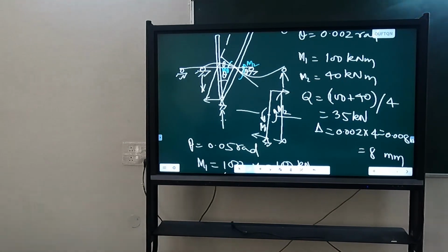What are the steps we have followed till now? At last, while taking the ductility, I have considered the ductility of the beam which has low ductility, that is beam 1. It is coming 10, and for beam 2 it is coming 25. So I have considered the ductility 10 for taking delta u. So what is wrong in that?